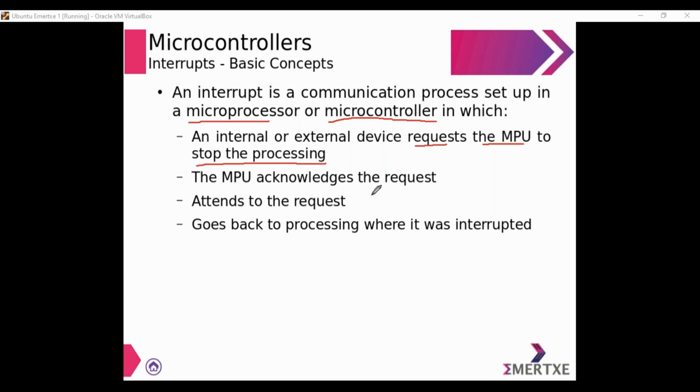So it is like a request which will be raised by either the internal device or the external device for the processing unit in order to stop processing the task it has been doing. After receiving the request, what the microprocessing unit has to do is acknowledge the request. Whatever request it is receiving, it has to acknowledge and attend to that request.